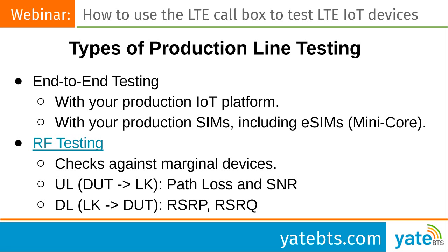So what we're going to talk about here is RF testing, and there are two types: uplink, which is the communication link from the device under test to the LabKit, where we're worried about what we call path loss and SNR, signal to noise ratio, and downlink, which is from the LabKit to the device under test. What's happening in downlink measurements is that the device under test is reporting back to the network how it sees the network signal on the downlink. So downlink testing is actually based on measurements received back from the device under test.